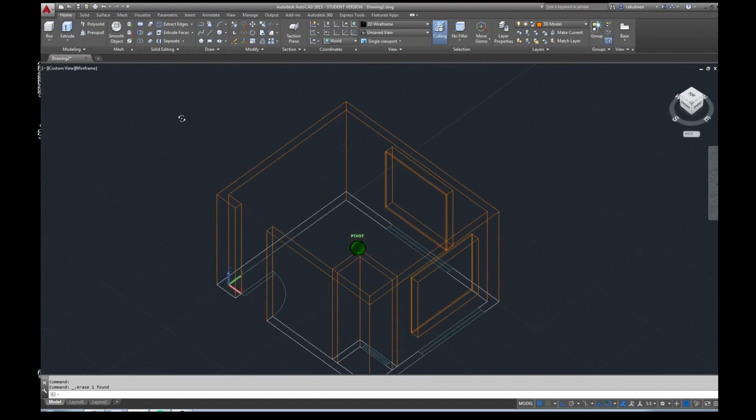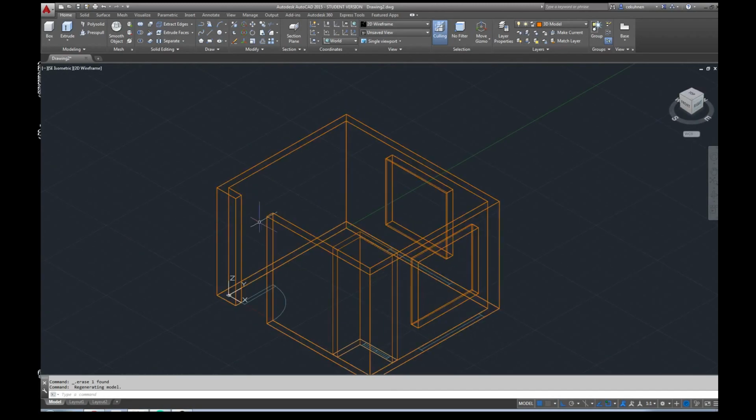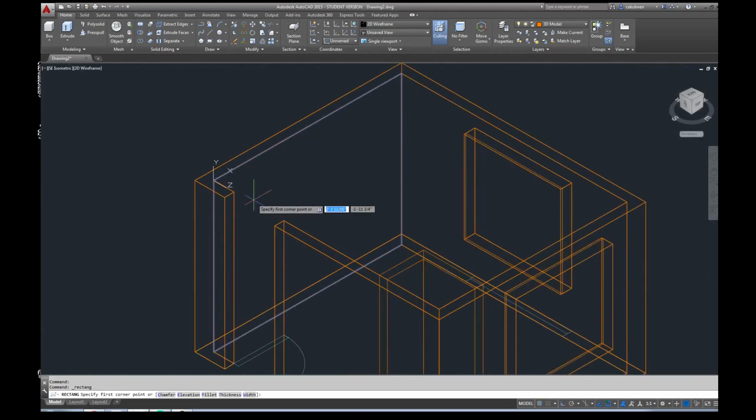So if, for example, I would like to create something here, I mean my door is actually open and I would like something else to be there. I could actually create a rectangle and from there, for example, to here. See, I snap to the top face. The main reason is now I can select this part, spacebar, and simply drag it down.